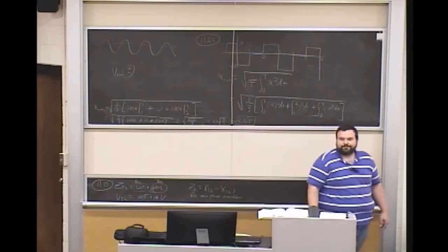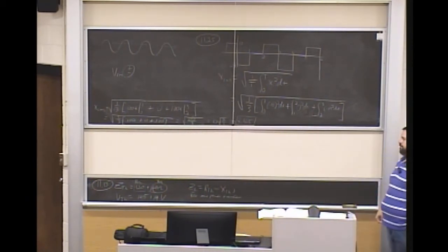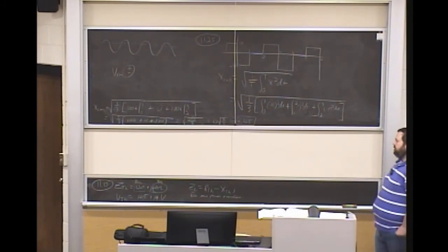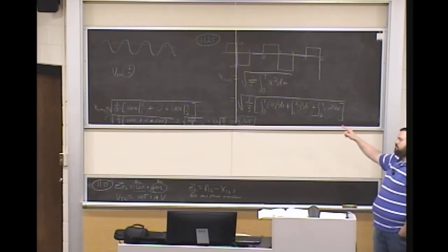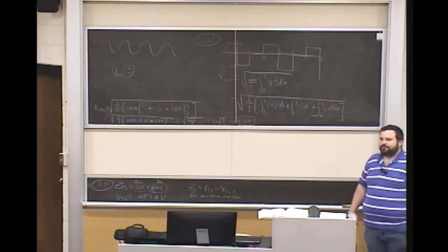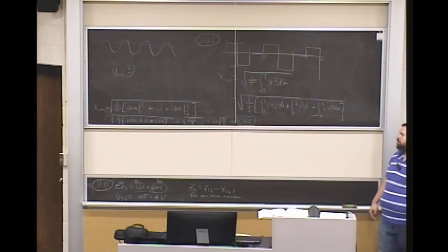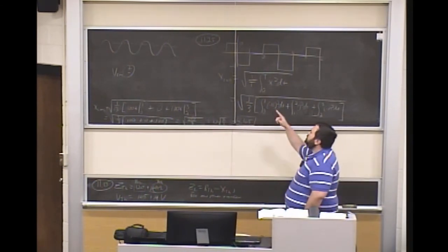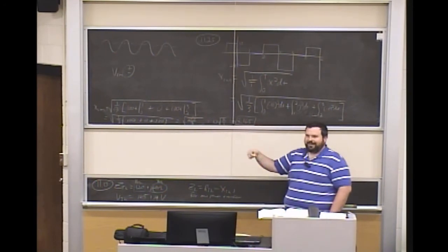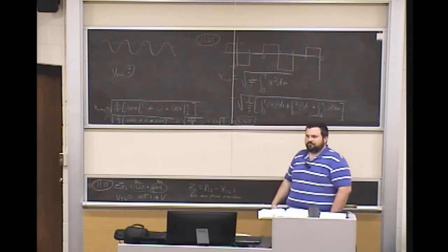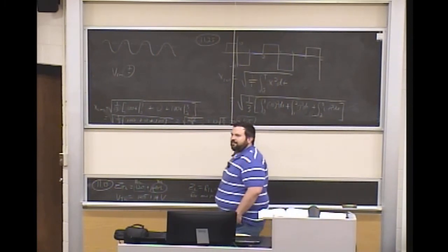James. So even though it's a negative voltage, it's still producing a positive power. Yep. On average. Well, because at that point, you may have a negative voltage and a negative current. So when those end up being multiplied together, negative times negative becomes a positive.